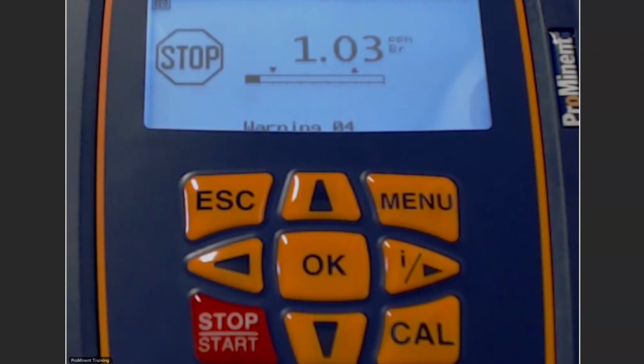So if we wanted to have some automation on how we adjust our set point, we could do that with option 2. Also a feed forward signal, we can use that for channel 2. And we can also change some of the control parameters with a digital input.